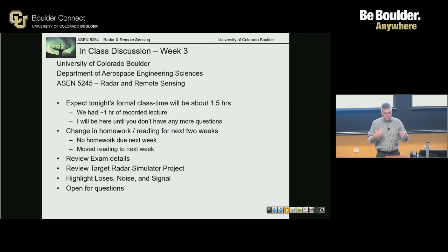If you were to create code, you would create a dwell engine that would say, what's your trigger? Start your trigger. Tell the transmitter to start making a pulse. It will create a pulse. Then part of your logic would be, tell the receiver, do not collect any information, blank it, until you know it's safe for there to not be any power coming back.